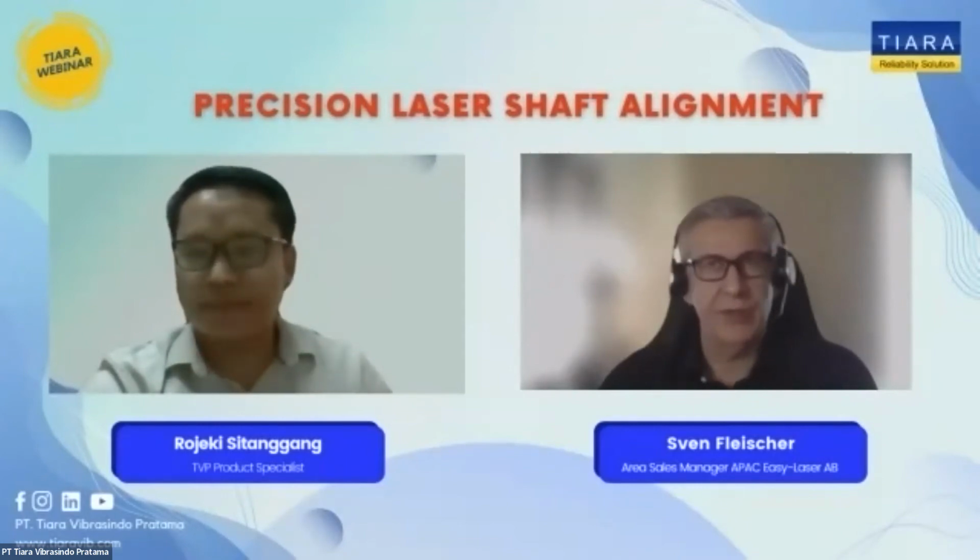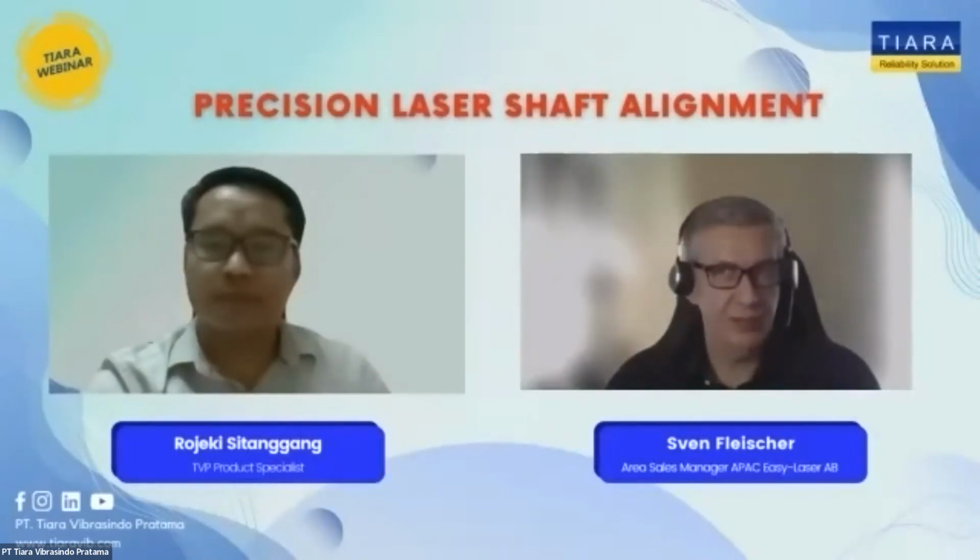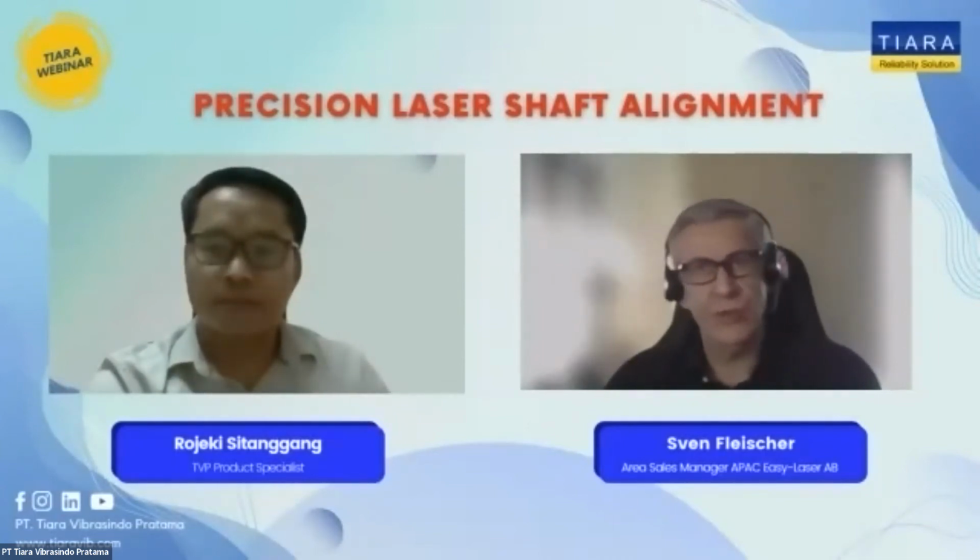When we talk about the correction, yes, absolutely. I demonstrated the alignment, that means the correction of the machine, without changing the position of the shaft. That is possible with the XT770 since it uses a 2-axis PSD in both measurement units.